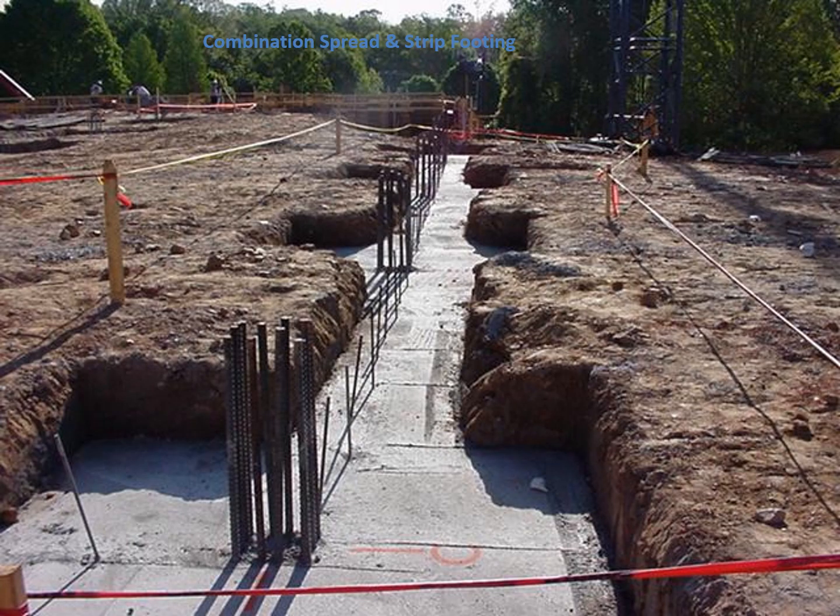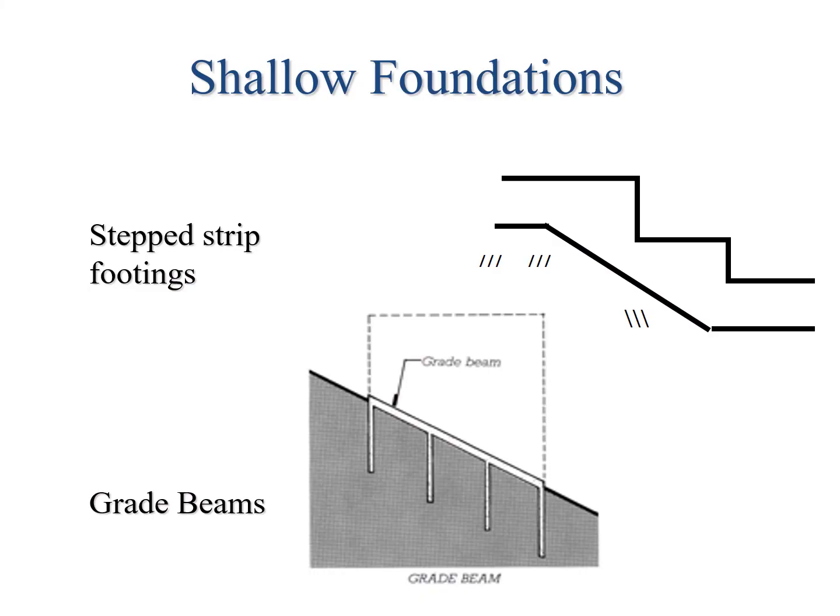Another look at the shallow foundation here, what it looks like as it's dug out. You can see the earth adjacent, all cleaned out and built away from it. The footing is, of course, with the rebar sticking out of it from the top, and on top of that will go the foundation wall. That's why that steel is placed right there in a straight line.